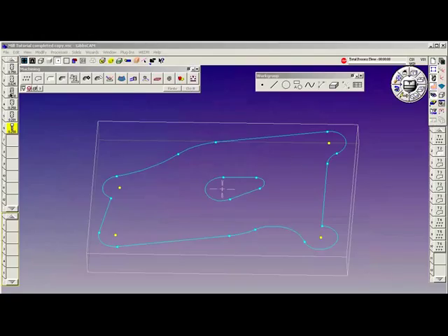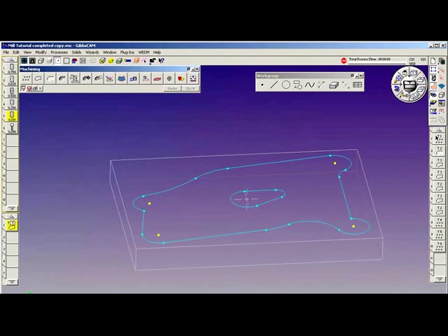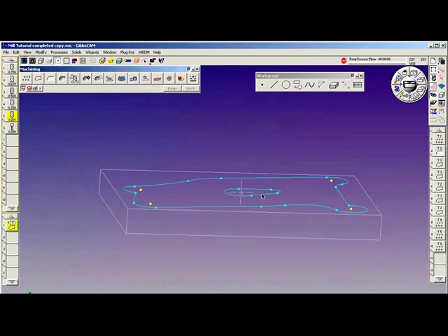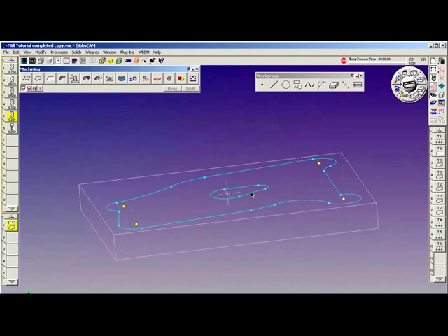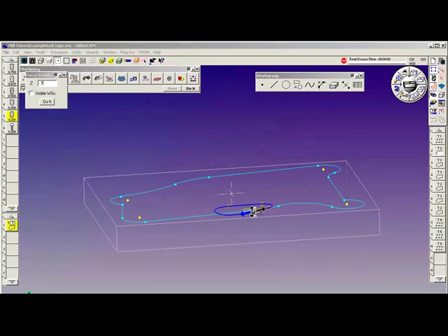Is our 1/2-inch cutter. Bring down tool number 3 and the contour tile. Let me close the contour tile just to illustrate something. Presently, the geometry resides at the top of the part. I'm going to use this cutter to cut a taper along the side of the end mill, but I prefer to start the cut from the bottom up. So I'm going to take this geometry and modify force depth to -0.5. Do it, and it snaps to that location.